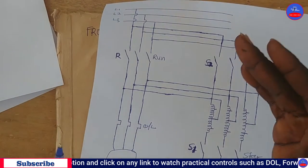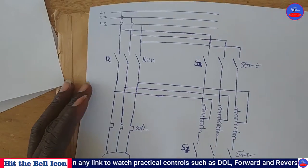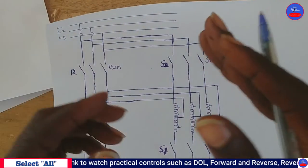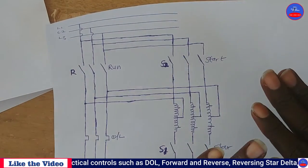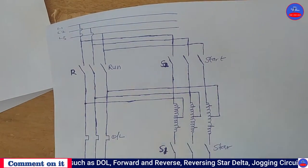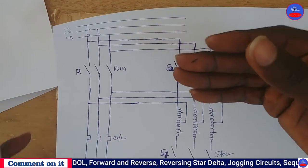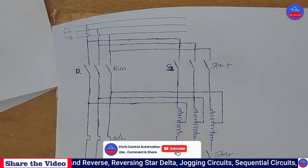We have open transition and then closed transition. The open transition is used on motors from 5 horsepower and below. Open transition is used on motors from 5 horsepower and below. And then closed transition is used on motors above 5 horsepower. Now let me tell you something here.